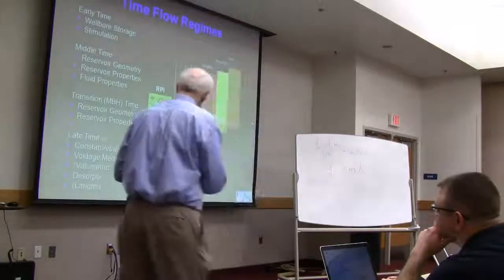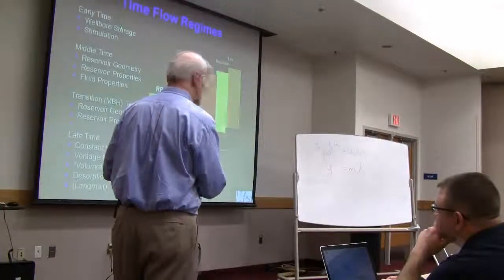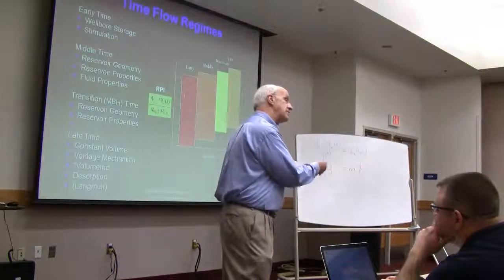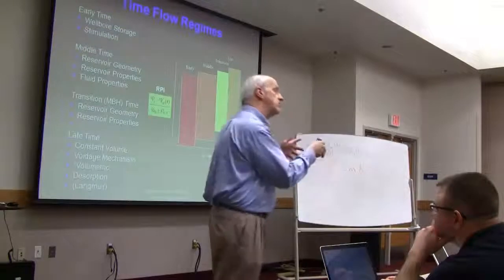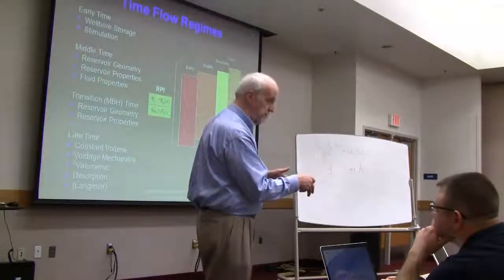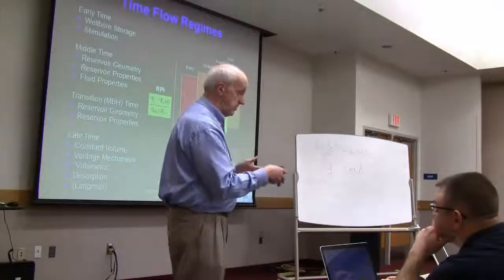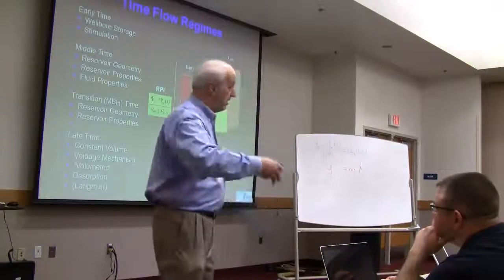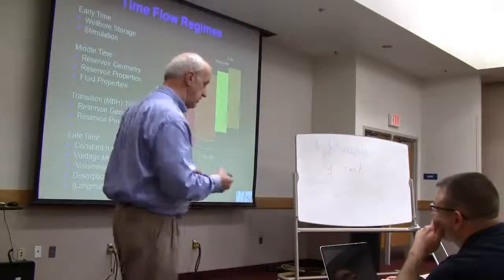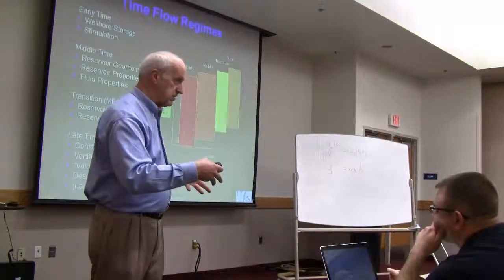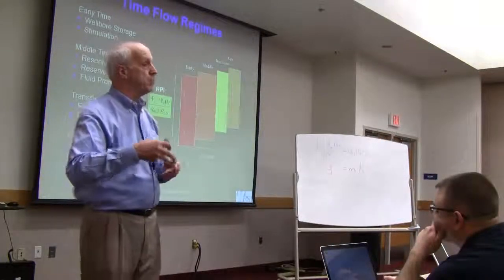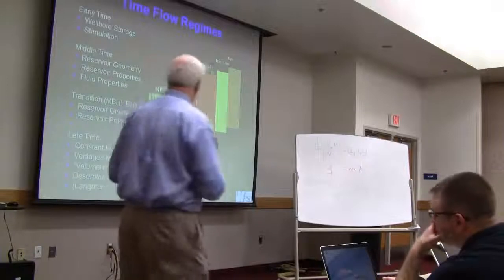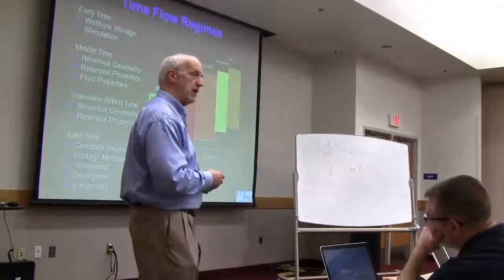So I'm confronted with the fact that this early time piece is the time looking at the behavior of the system where I spent money to connect to the natural fracture system. Then comes a time when I look at the natural fracture system and its connection to the reservoir. Then I'm out into this middle time response. Then the reservoir's response. Then the transition once the pressure wave hits the side of my pond, and I'm going into pseudo-steady state. And then I'm in fully dominated pseudo-steady state, or fully boundary dominated response.